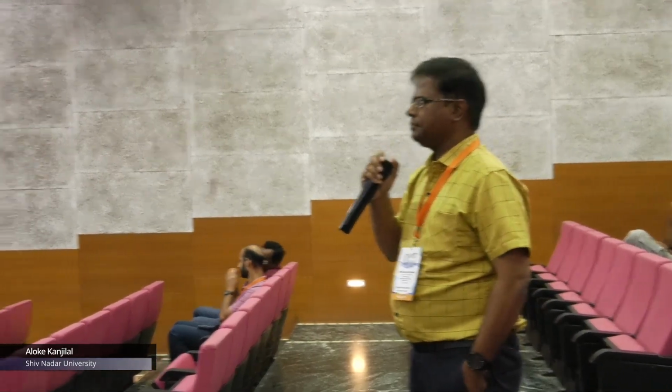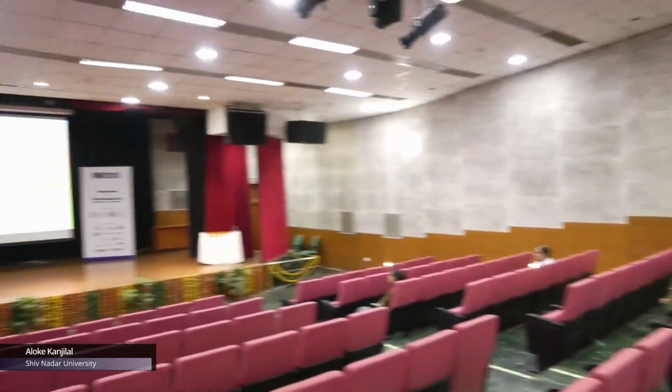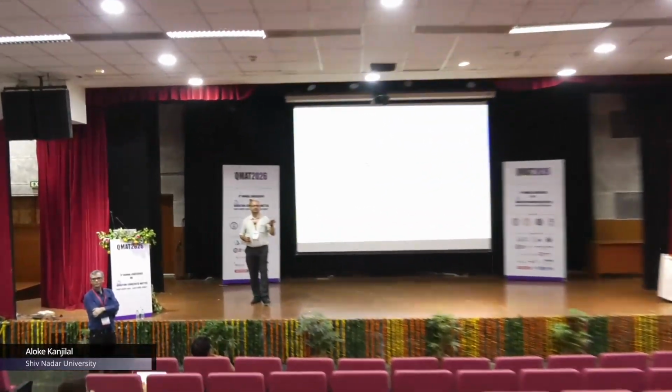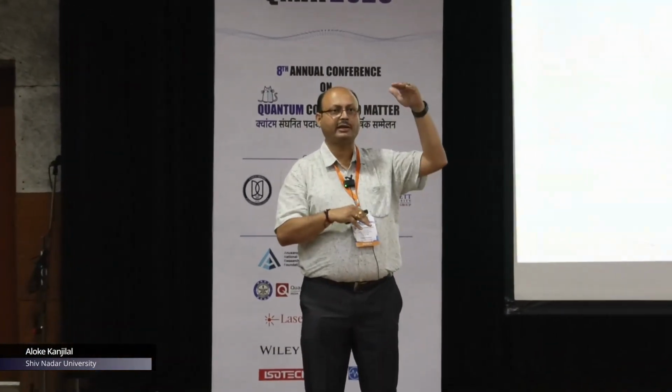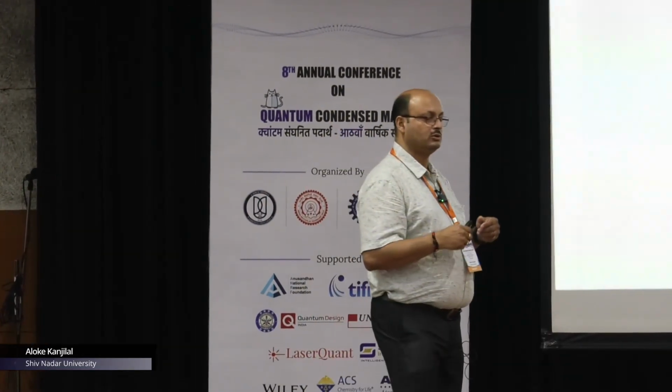Thank you, nice talk. I would like to ask what kind of interactions you expect between this hBN and hafnium oxide. That is my first question. The second question is what kind of band gap your hafnium oxide is showing. hBN is already known to be around 6 electron volts, and hafnium oxide near about 4. So band gap wise, the current cannot go there because there is a high band gap for hBN.